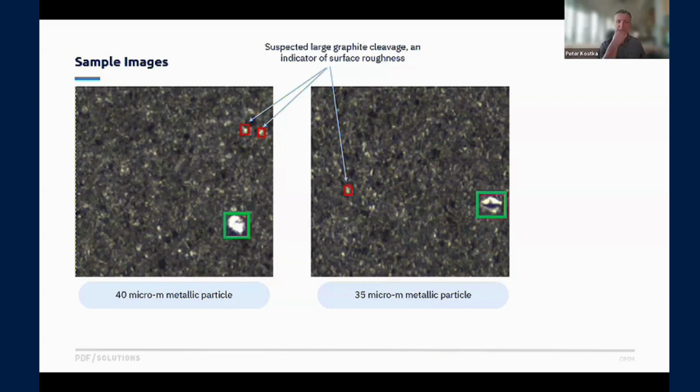And then again, based on our experience looking at aluminum versus steel, in most cases there's a pretty obvious difference in appearance, mostly coming from shape and almost texture, where the aluminum particles that we've seen in cell manufacturing are more malleable, and you can actually see the edges are softened, versus anything that we've seen in manufacturing which is coming off of steel is a lot sharper.